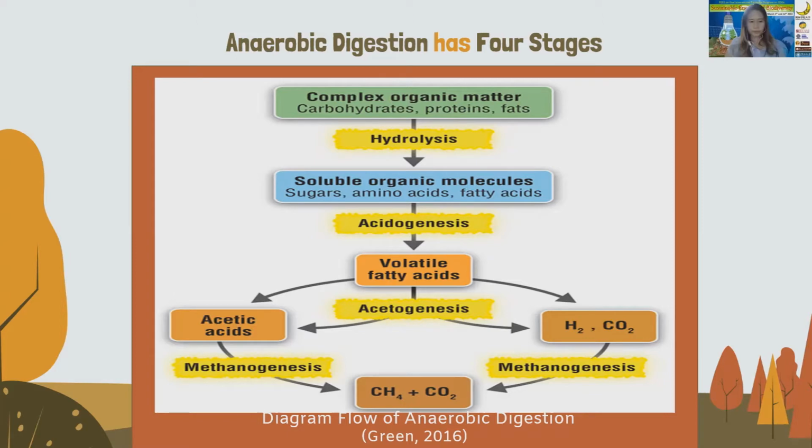At the acidogenesis stage, facultative fermentative bacteria respond to conditions where the stage is characterized by the product VFAs, or as we can see in the diagram, the volatile fatty acids. These VFAs from the acidogenesis stage will be converted in the acetogenesis stage to become acetate, with hydrogen also being produced. This conversion is a vital process because the higher concentration of hydrogen and carbon dioxide can be reduced to the production of acetate. So it is really important to make sure that the hydrogen partial pressure is low.